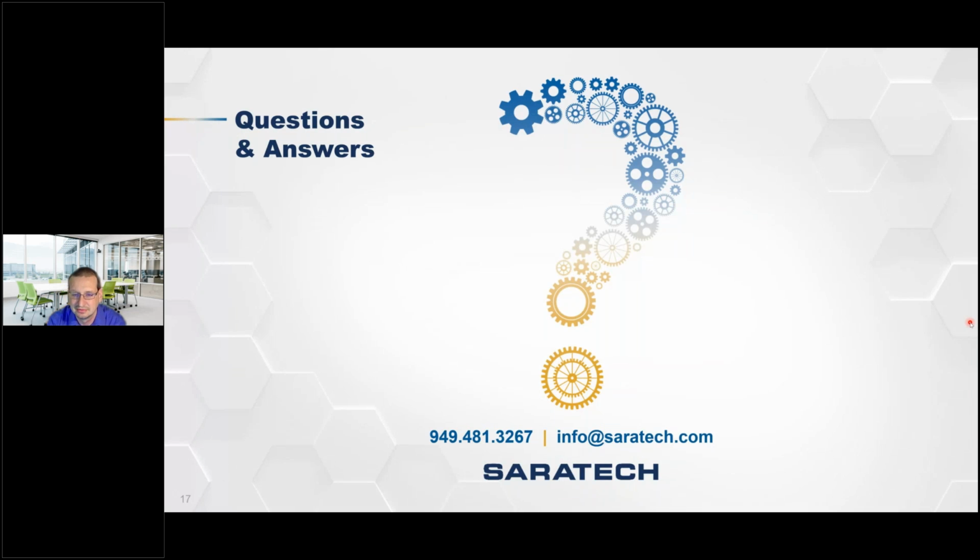Okay, thank you. And then next question is, can gap elements be used to model ropes, cables, or strapping? Yes, you can definitely use that. That'd be the opposite of the presentation here, but you can definitely use them in tension-only situations. They work just fine for that, as far as I can tell, from my couple exercises I've done in it.